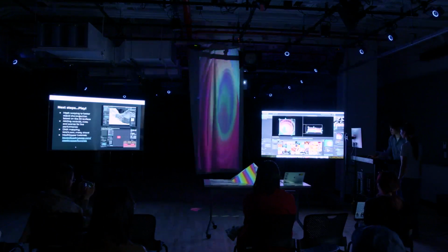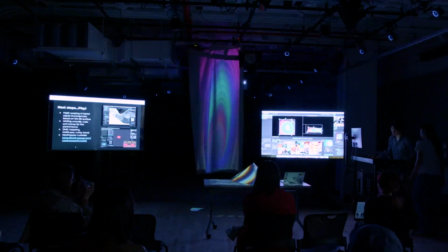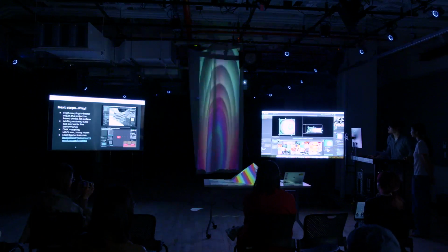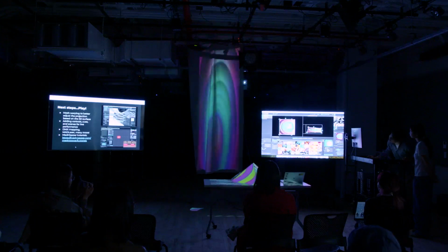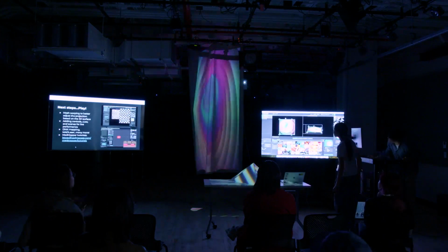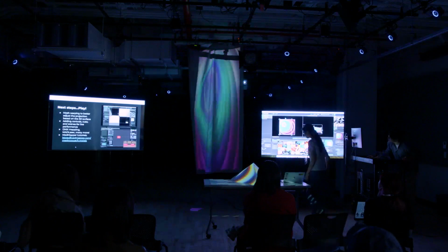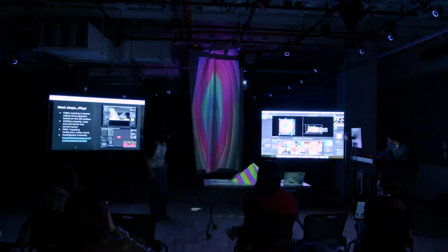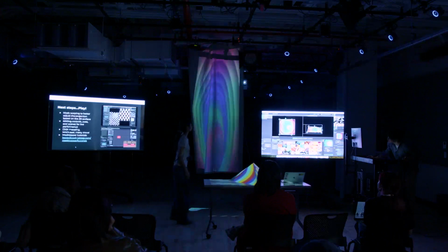And you can also here enable the warping point. You can also add it here, but usually I just right click directly on the perspective. So it looks like this side. So we can just move this warped geometry by the grid. And it looks like the bottom is bleeding a little, so I can just add another warping point and then drag this in.